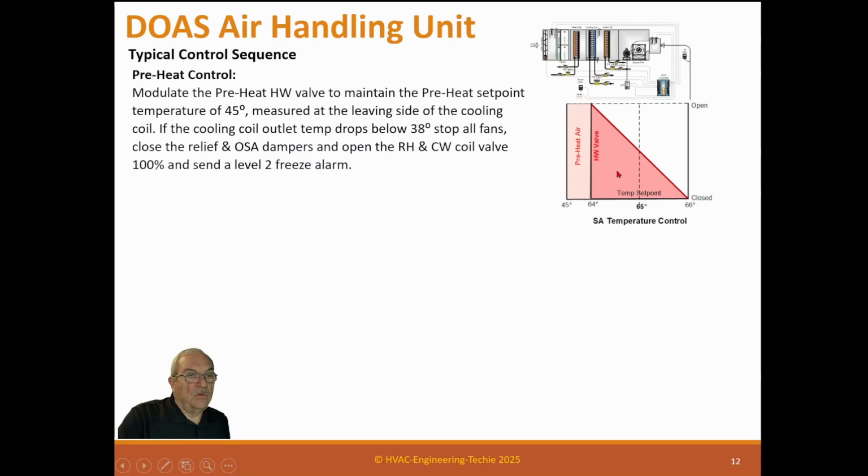So this coil is actually designed to take the cold outside air, which may be freezing, and raise it up. But if it doesn't do that, then we need to shut everything down because it's going to freeze these other coils. So basically we turn off the fan. When it gets to freeze protection, we turn off the fan, open these coils to make sure that we're actually using the chill water to warm it up.